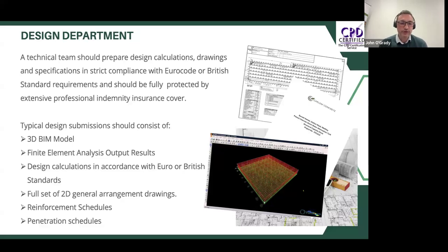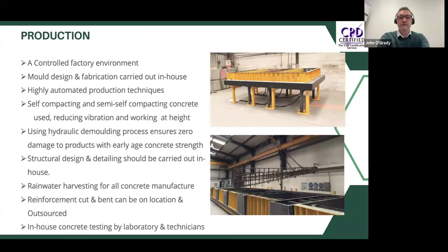Other things that follow them would be things like reinforcement schedules and penetration schedules. And in the design, sorry, I just skipped ahead, but in design, it's important to factor in things like ground conditions. Not everybody will look at that. They might give you something standard and not have a look at the soil conditions, the water table, etc., which are very important, and we'll touch on that a little bit after.